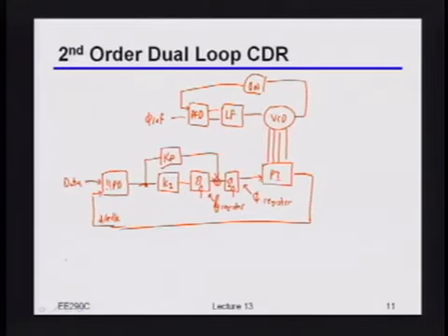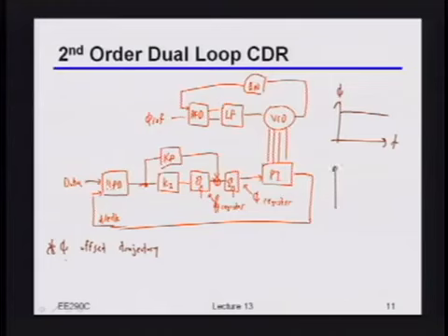Okay, so the higher order bit to keep in mind here is that whenever you're building these CDR types of loops, the really important thing for you to look at is what the phase offset trajectory is. By trajectory I mean, we said that in a mesochronous system, the phase versus time is basically constant, so it looks like that. And that means that when you build the loop, a first order loop is fine, because you just have to figure out what that offset is. If I have a plesiochronous system, then my trajectory has this ramp. So again, I better build my loop so that it can estimate both that offset and the ramp rate.